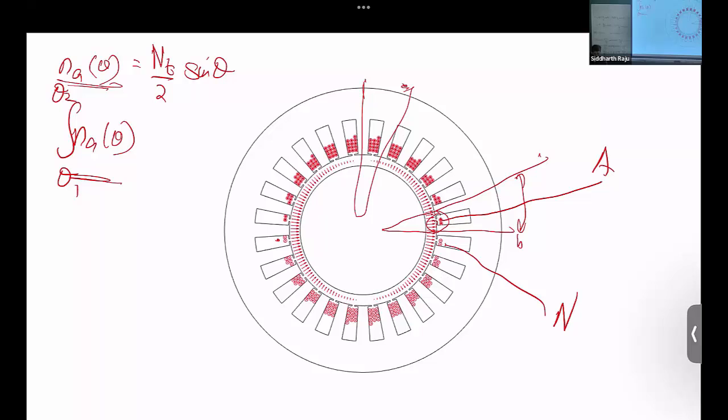In the case of a DC motor, the windings close on themselves. In the case of an AC motor, they don't. You start with one winding coming out, and a separate terminal comes out. When they wind the other two phases, those again would have a B phase and a neutral wire, and a C phase and a neutral wire. If your winding is balanced and you have balanced voltages, then the current will also be balanced. That means the sum of the three currents will be zero.